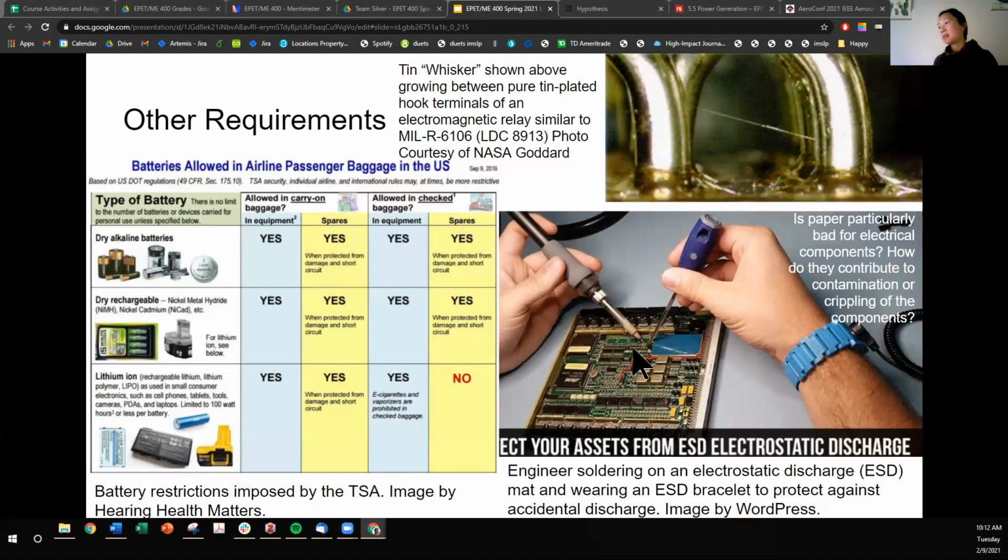So sometimes you waste a lot of time by having this component damaged, and then you have to debug, and it turns out that because of bad electrostatic discharge hygiene, this component broke and you have to replace it. So like, just blanket statement, when you're working with electronics, try to be in an electrostatic discharge safe environment. Have good practices when working with these components because they are sensitive, and you don't want to waste time or break components, which is wasting money.